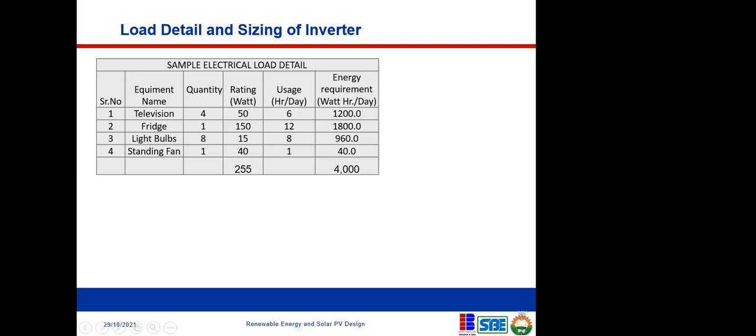So the most important thing is the load that you want to power. You need to first of all take an inventory. You have to do a load audit of the load that you want to power to determine the energy that is required and the power that is required to meet those loads. Mind you, energy and power are two different things. These two things are very important: the power that is required and the energy that is required. If you have these two things, then you are good to go.